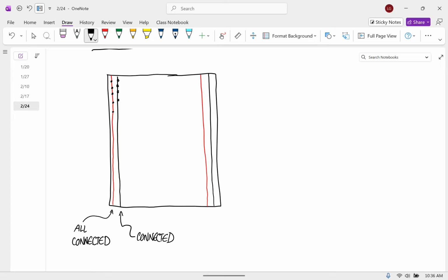And then the other connections are groups of 5 holes. You have a whole list of those, but those horizontal rows are connected, and only the 5 on each side are connected. So these are connected, and these are connected.